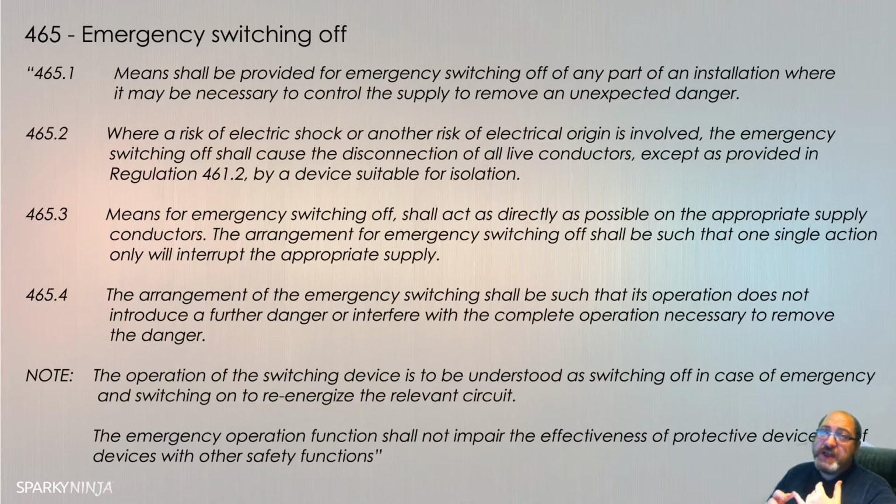We then moved on to protection against overcurrents, where we talked about the whole issue of fault loop impedances and all these other things, where we established a low impedance to achieve a high fault current. Towards the end of the protection against overcurrent, we looked at calculations, t equals k squared S squared over I squared, which told us the amount of current that would be occurring in the fault condition and whether or not the live conductors would be able to carry that current or would tolerate the temperature change for their insulation during the period of that fault.